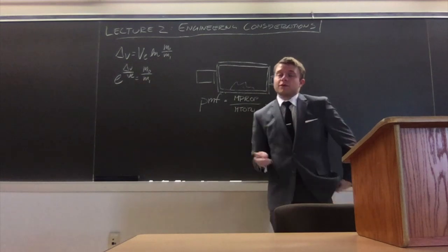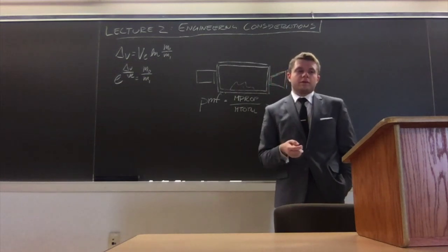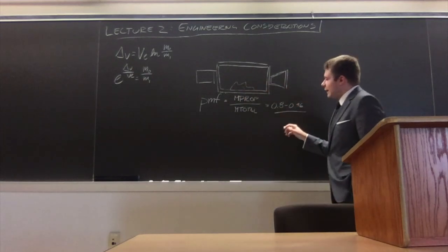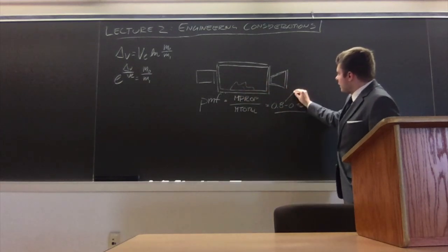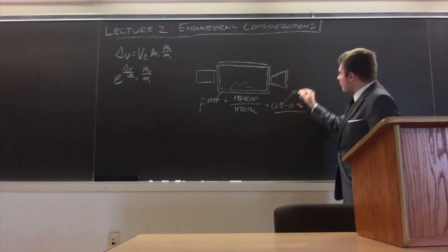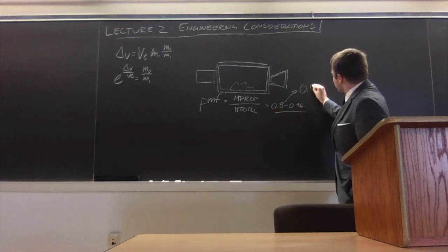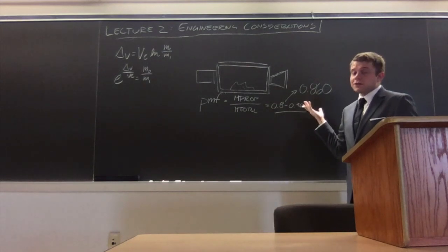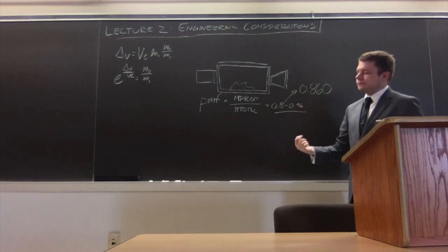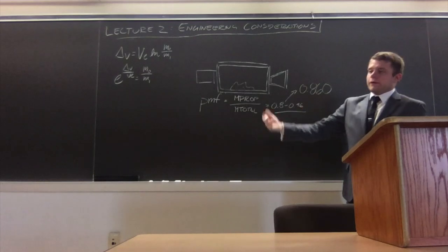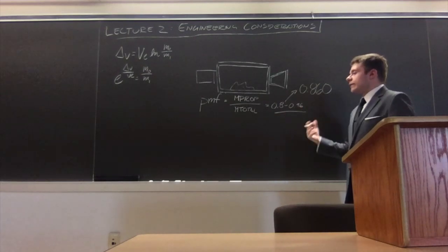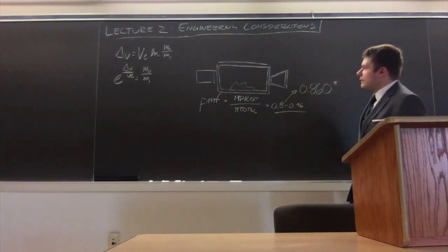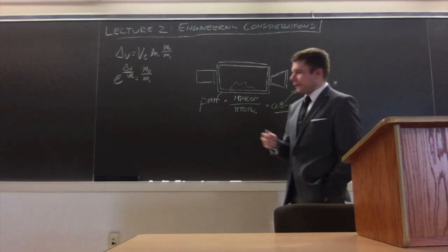We're not going to be playing with this so much because we mostly are focusing on solid rockets. We still have to make the same general consideration. And what we're looking at solid-wise is probably a number of about 0.86. This is a number that I've come to after doing a lot of research into this question and comparing solid rockets to one another and coming up with a general average. But there's also a little caveat to this, and this caveat has to do with scaling.